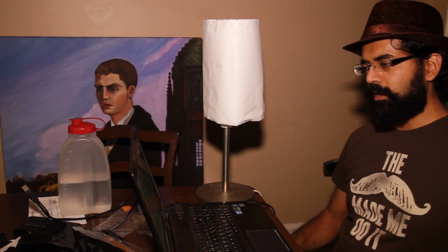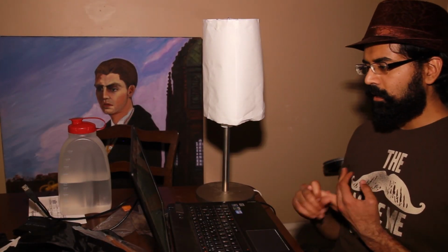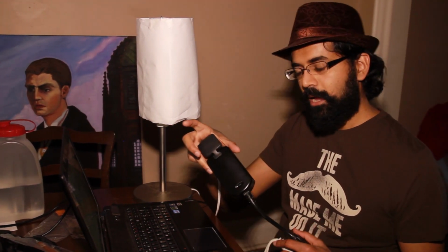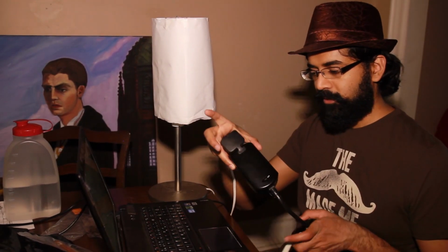Now that we've got the controller software installed, the Z-Stick's driver software installed, and the firmware on the Z-Stick itself updated, and the Z-Stick included with the GE outdoor module, we're just going to go ahead and test whether the whole thing works or not. And so I just plugged in this lamp here, this ghetto shade, right into this piece here, and I'm just going to hit power, and I hear a click and the light turns on. I'm just going to hit power again, click, light turns off.